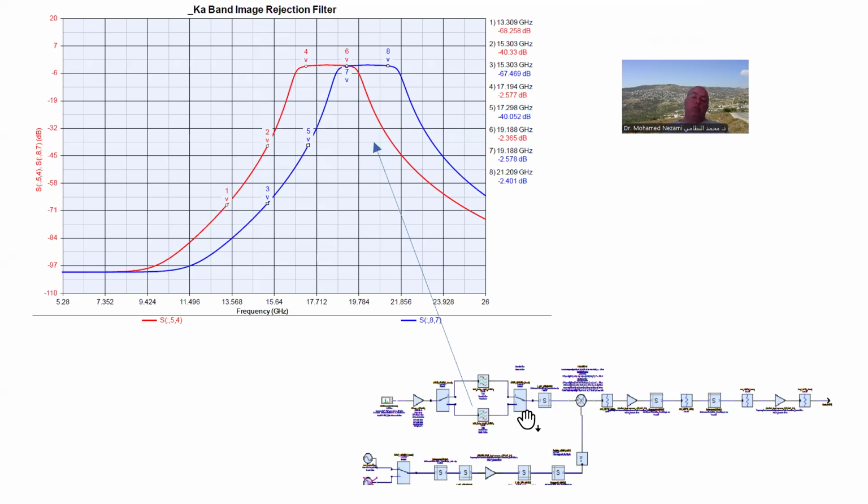For instance, if you were doing this for 5G with a strong signal for a radius of a few kilometers from the base station, you might say, well, I can have 3 dB of noise figure, and then you may not need a critical front-end filter like I would here, assuming that your antenna is not picking up interferences.